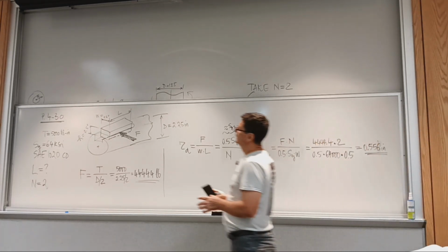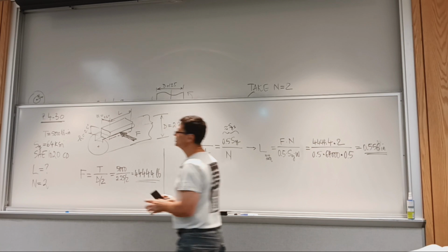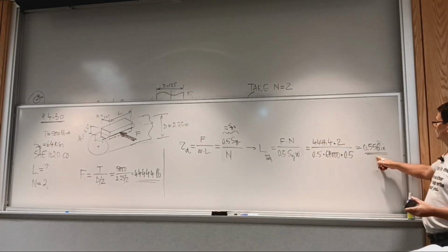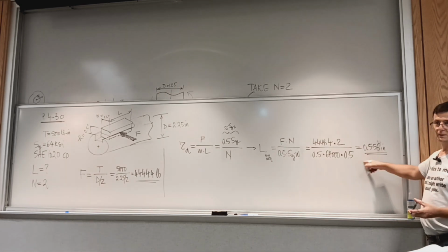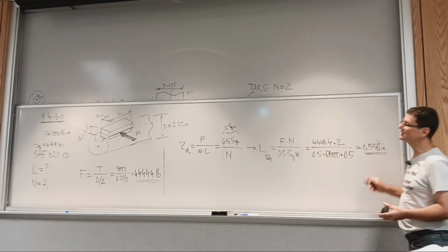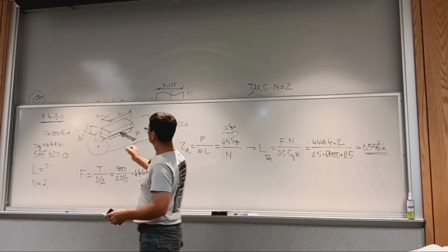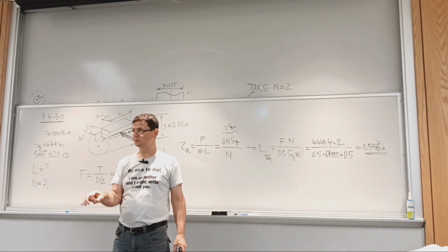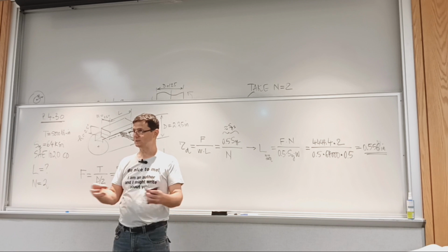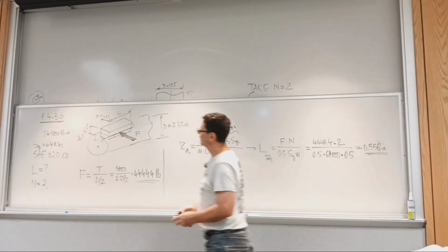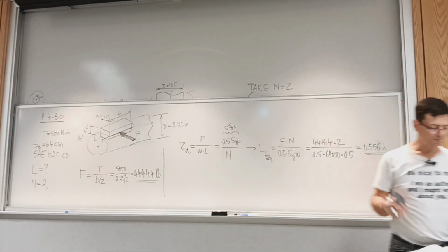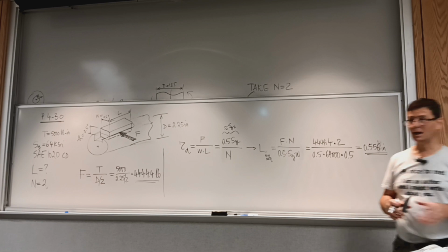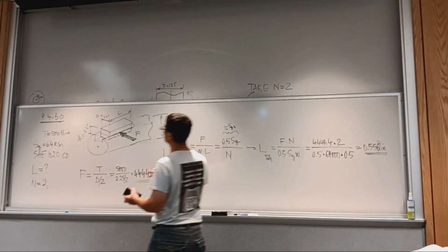And this is where engineers flex their muscles, because on one hand, this is not a preferred size, firstly, and secondly, you don't want to have a key that looks like those cheese cubes you can buy at HEB. Your keys are usually longer, right? So you need to match it with the size of the hub to get a good portion of it.